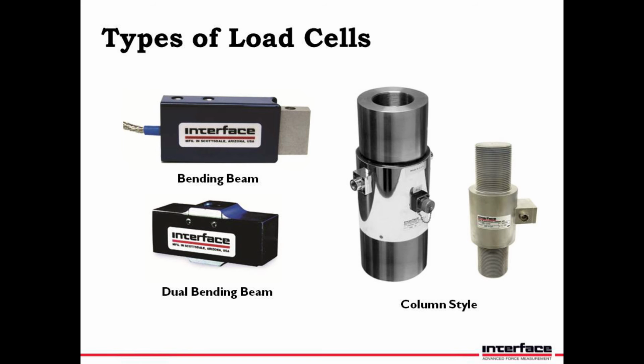Then moving on, types of load cells. Now, oftentimes, the type of load cell will be decided using the customer's constraints, more or less. Oftentimes, a customer will have a certain accuracy requirement. Perhaps they're using it within a hazardous environment. Dimensional constraints are common constraints that I see within my daily work. And then capacity is also relevant, cost, and then the type of loading, how many cycles are going to be performed with this load cell, and will it need to be fatigue rated.